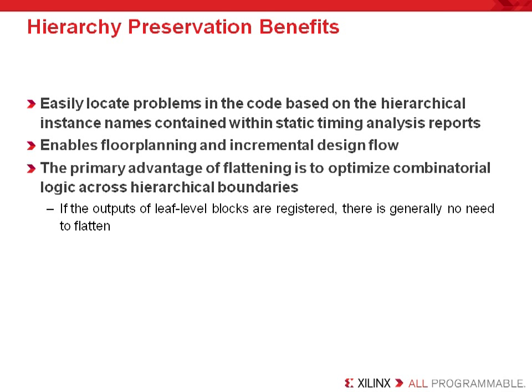Note that most experienced designers know that for optimum speed they need to make sure that critical timing hierarchical boundaries have registered outputs. This is a pretty standard way for users to tolerate a high fanout net that a component might be making, or if they know the placement of the destination logic might be far away. But commonly when a designer makes a purely combinatorial piece of logic, adding a register can easily be accomplished by converting the component to a registered component. If the component already has its outputs registered, then optimizing across a hierarchical boundary will have no effect since logic optimization won't remove a register in that case.